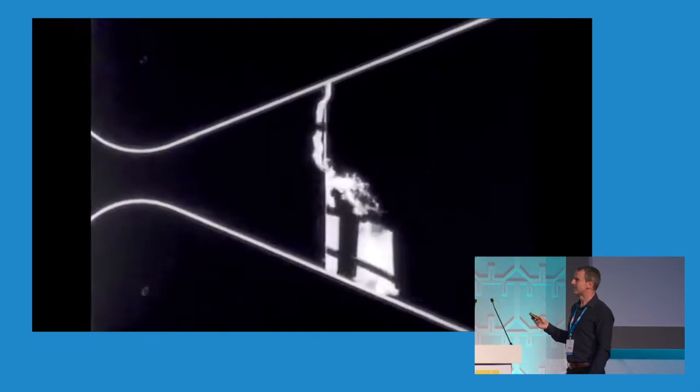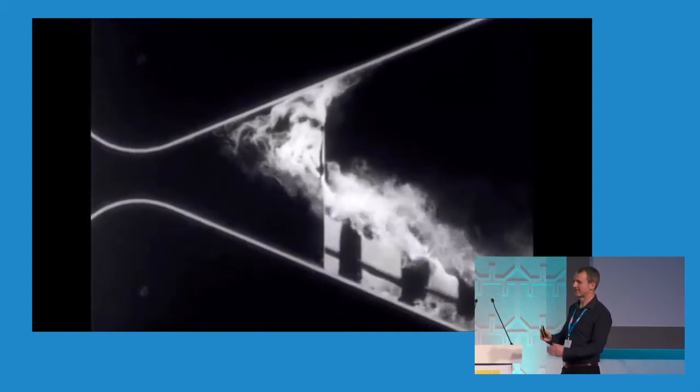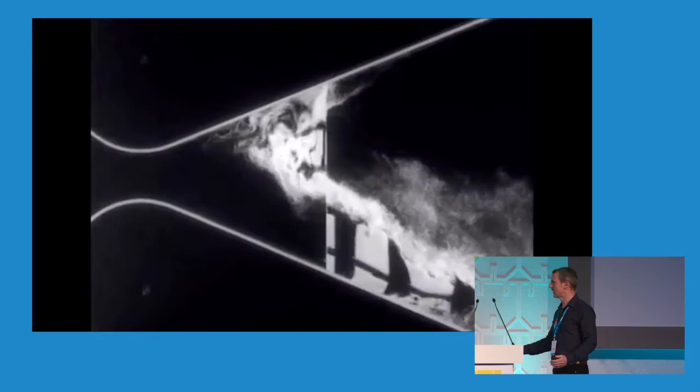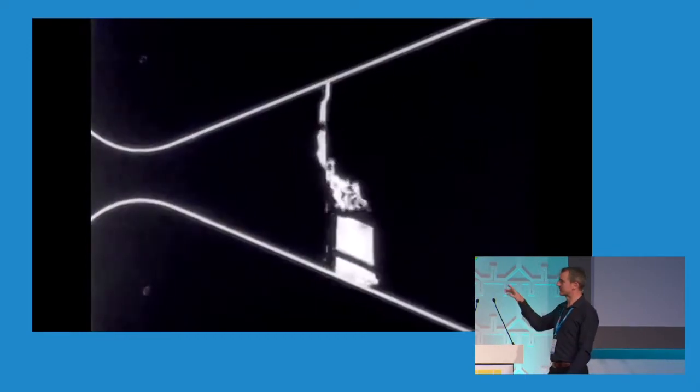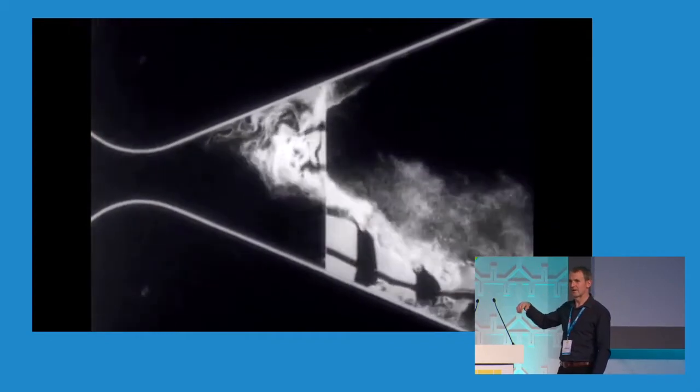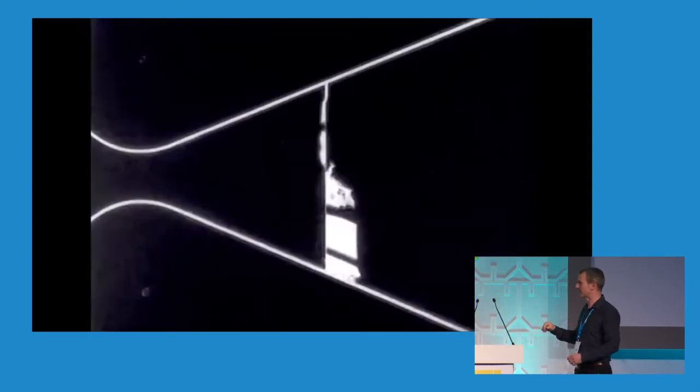This kind of helps to visualize the biggest problems that we have with flow, and that's that it tends to want to stick to a surface. And that looks like it's a fairly gentle opening. And when you consider what happens with water flowing around bridge supports, for example, this is exactly what you'd get. Anybody that's been canoeing in a fast-moving river will probably have been in a situation where they're suddenly going past a bridge support, and you find that the boat is being pulled back in towards that support, or it's turning around and around, and that's because you're sat in that kind of turbulent zone at the top where it's returning.